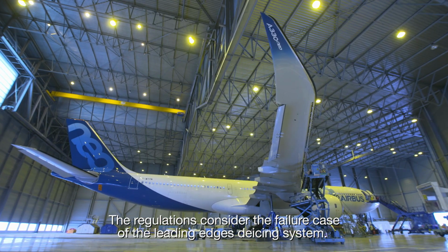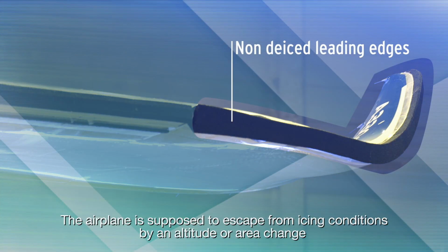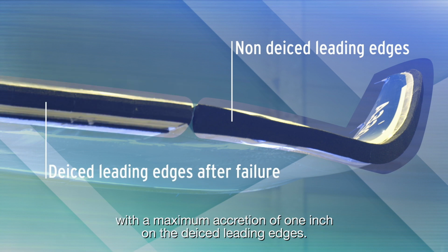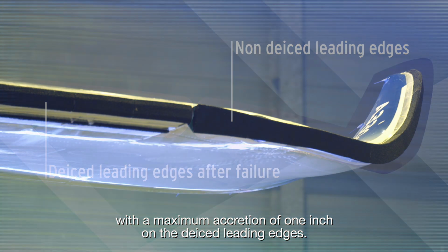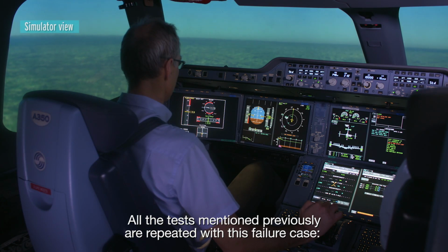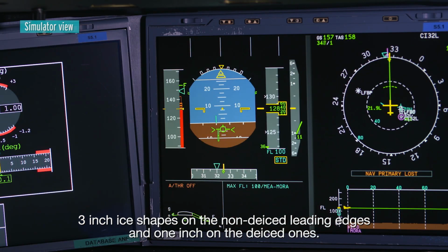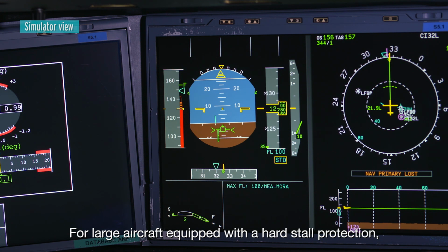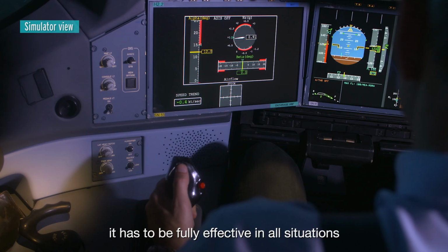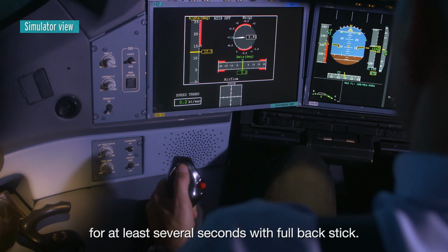The regulations consider the failure case of the leading edge's de-icing system. The airplane is supposed to escape from icing conditions by an altitude or area change with a maximum accretion of 1 inch on the de-iced leading edges. All the tests mentioned previously are repeated with this failure case: 3-inch ice shapes on the non-de-iced leading edges and 1 inch on the de-iced ones. For large aircraft equipped with a hard stall protection, it has to be fully effective in all situations for at least several seconds with full backstick.